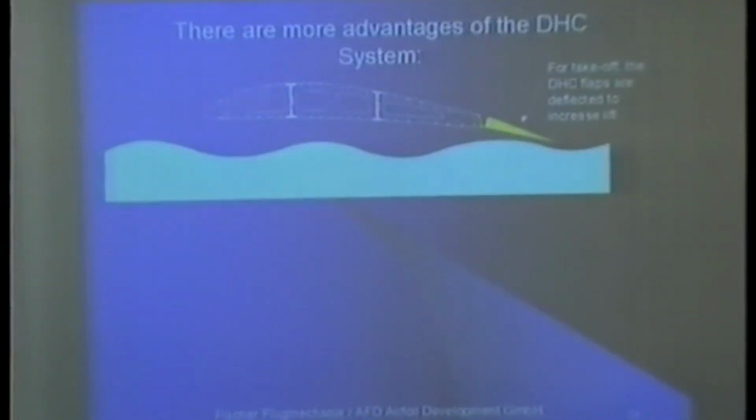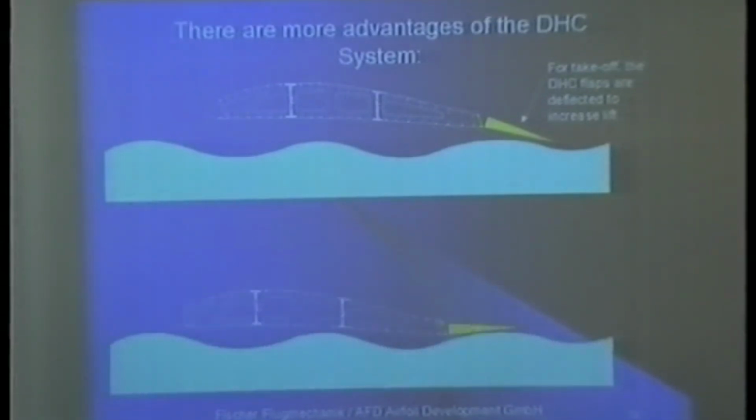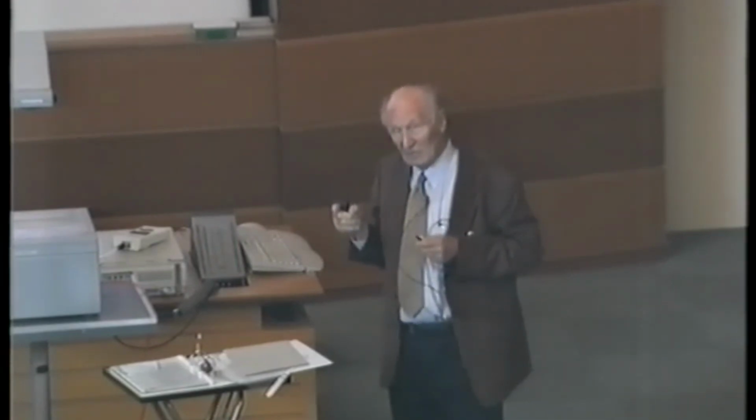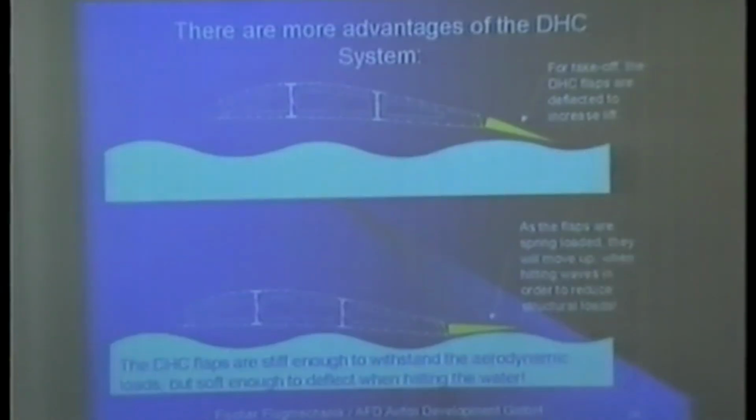And in addition, our flap segments are hinged on a main tube with dampers. And with these dampers, which we can control, they are made in this way that they are stiff against air loads, and they are flexible against water impact loads. So we reduce the loading during takeoff and landing on the trailing edge, and they are the biggest wetted surface. And when we have waves like that, with these dampers it fills automatically, it follows the contours when you make the right damping device.